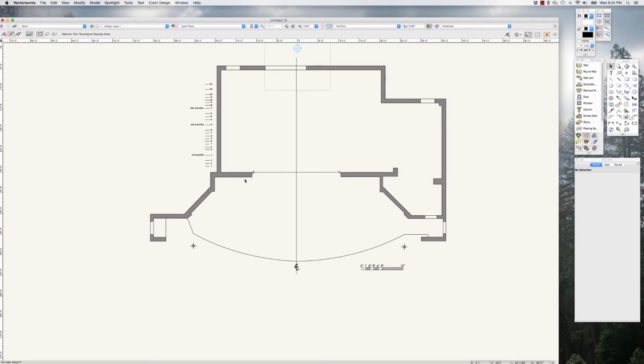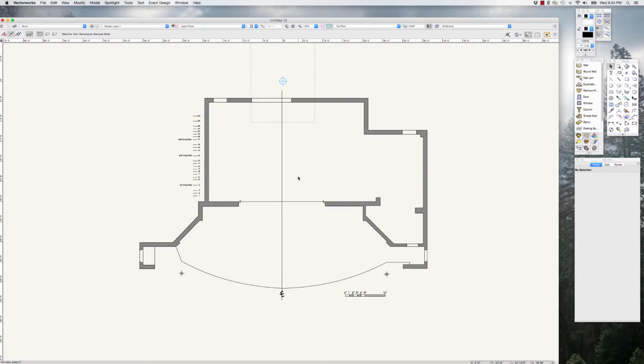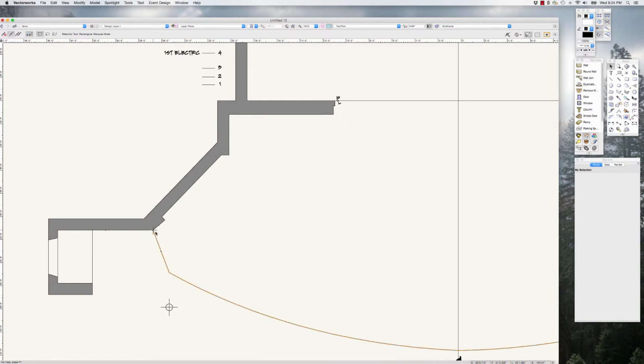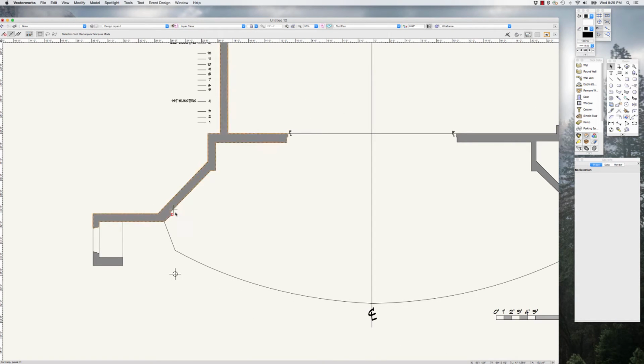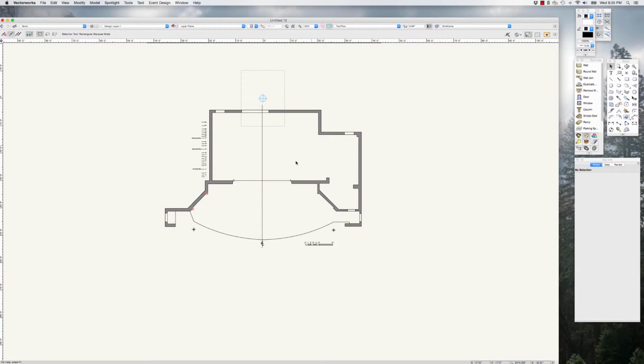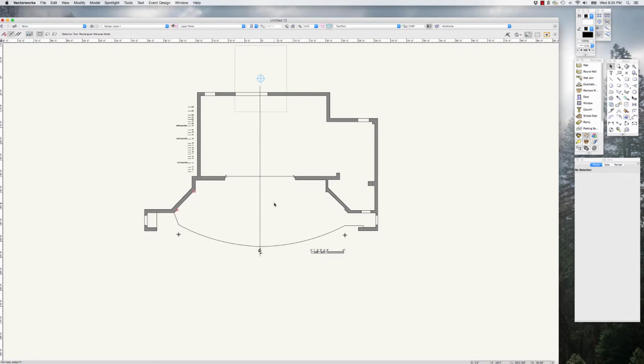So what we're going to do is use the shapes that we have here to extrude walls for the theater. You might ask, hey, we just learned the new wall tool in the last recording. Why are we not using the wall tool? The wall tool doesn't work very well when you have walls that are strangely shaped like these walls are. You can do it, but it's very time consuming. You have to build the walls and then go back and cut out notches, or you have to build the walls and then add onto them, and for what we're doing now, it just isn't worth the effort. So that's why we're going to do this as extrusions rather than as walls, even though we're going to have to go back and cut some holes in the walls in order to get the doors and the proscenium where we need them.